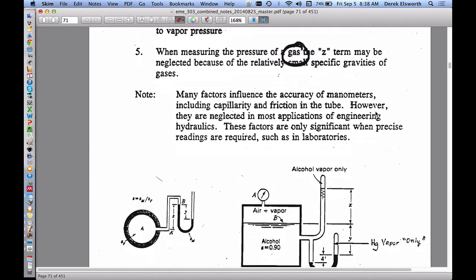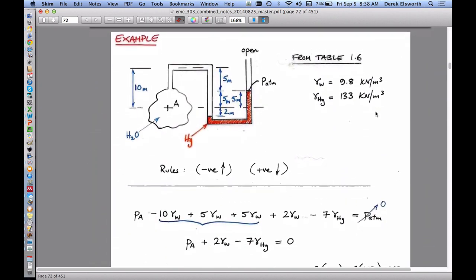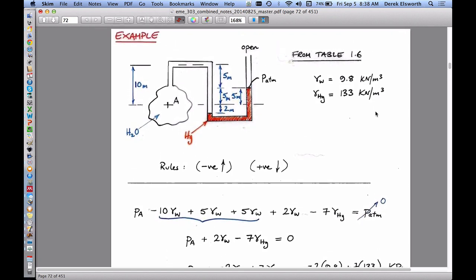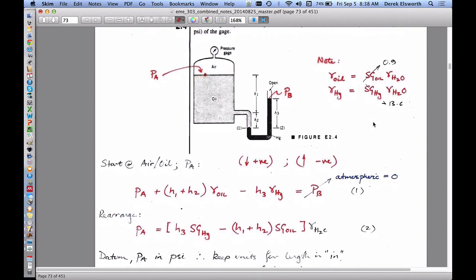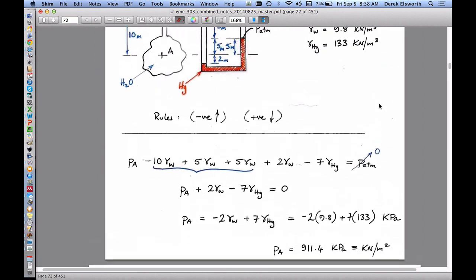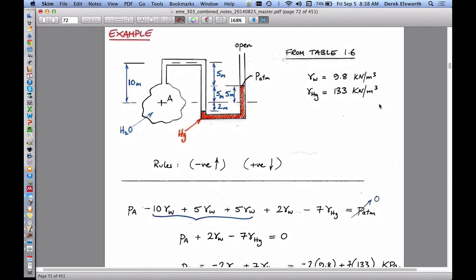So the manometer rules are written, but those are the only things that we're ultimately doing. We have a number of different examples. We can go through some more, but they're relatively straightforward to understand. For me, the easiest way is to first make one choice: the place where you'd like to calculate the new pressure, and that is the last term that you'll fill in your equation. And the first one is the one that is furthest linearly away from that.